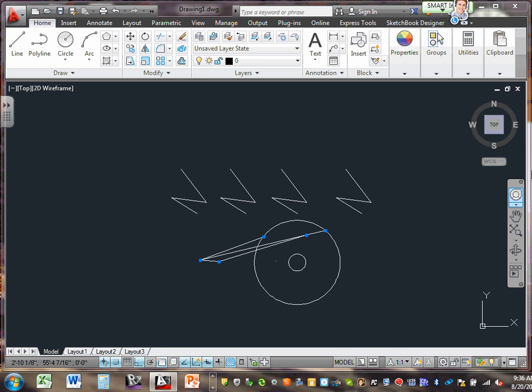Matt, here's what happened. You grab a little receptacle symbol and you put it on a parking lot, and it looks very small. You can't see it when you print. Oh my God, I can't see that thing. Typically, we bring them to scale, but say if that happens, you need to scale it. So if you grab scale, can you guys click on scale? I'm going to scale something so I can show it. I'm going to go grab one of these.